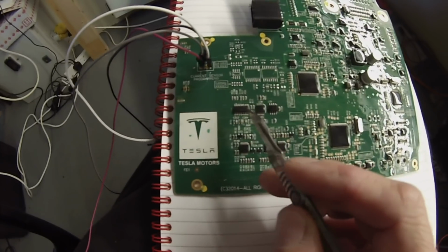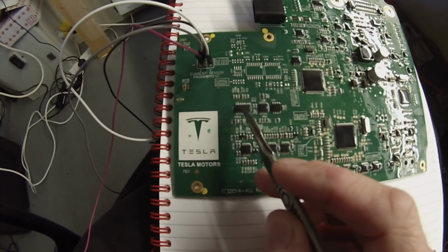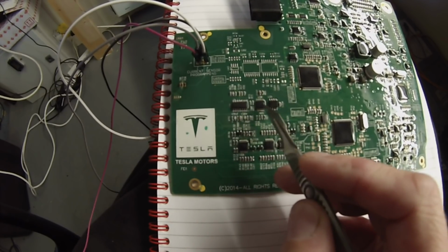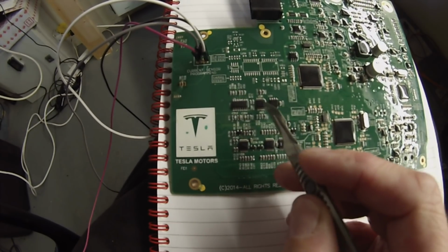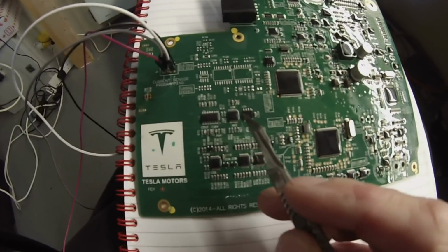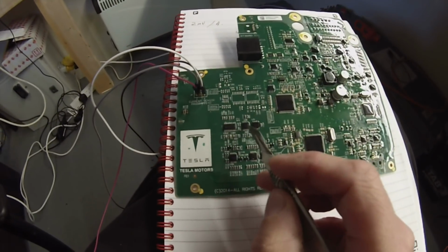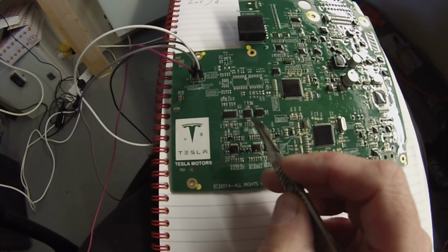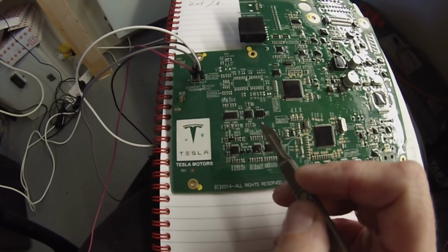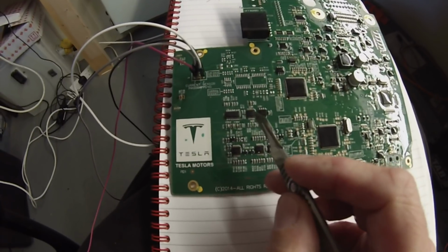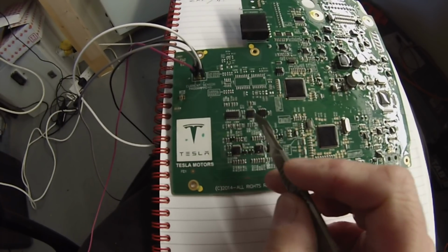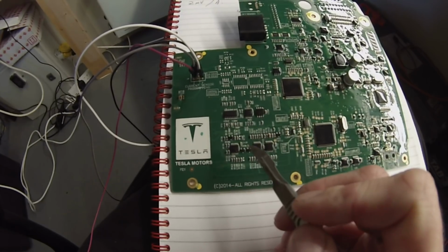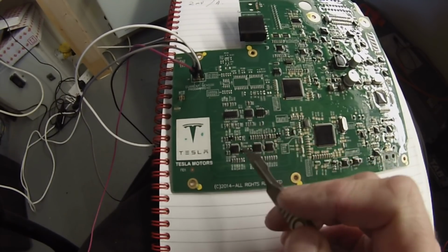Now, this is where it gets really fun, because once it comes out of the buffer amplifier, it goes into U38, this device here. Now, I'm going to give you guys one guess what U38 is. It's an LM2901 quad comparator. And guess what? It's used in the exact same way as we use the window comparator on the open source board.